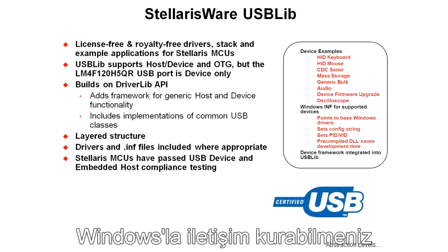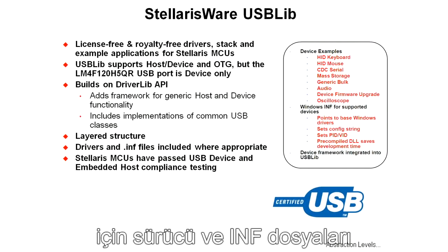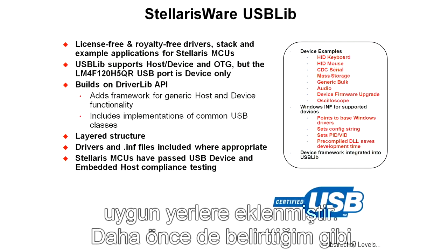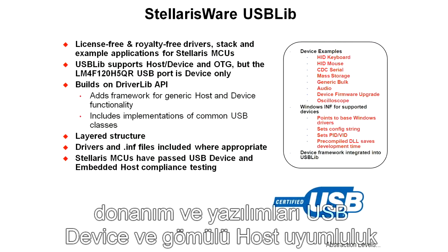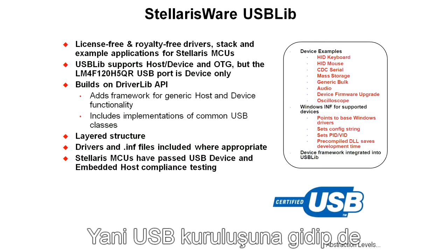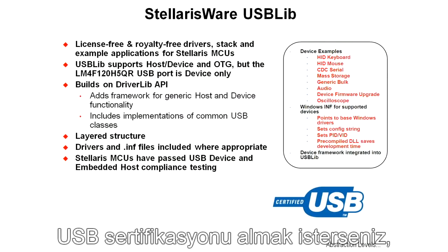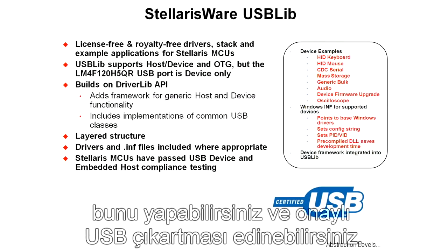The drivers and the INF files are included where that's appropriate so that you can communicate back to Windows with them. I mentioned before, the Stellaris microcontrollers, the hardware and the software have passed USB device and embedded host compliance testing. So if you want to get the certified USB certification from the USB organization, you can go do that and stamp your product with the certified USB decal.